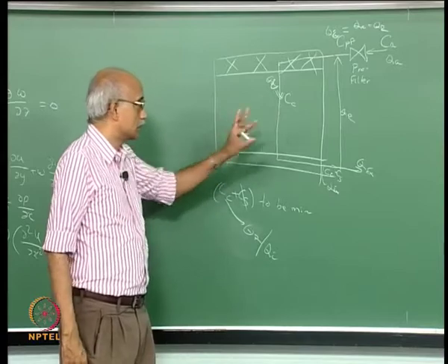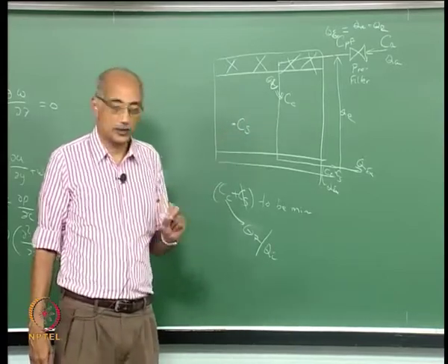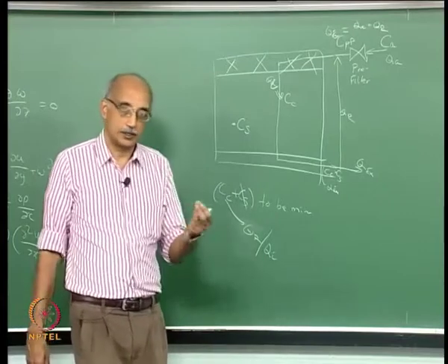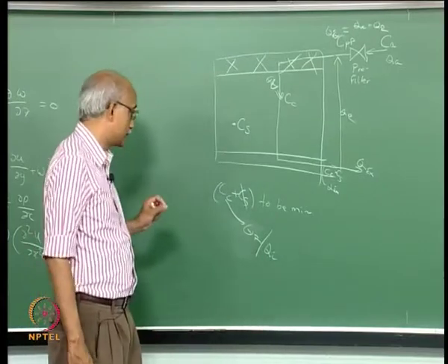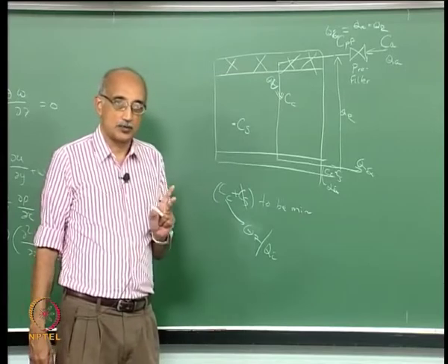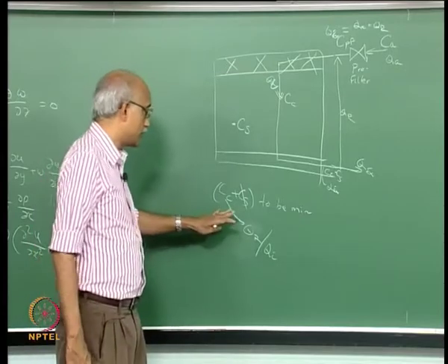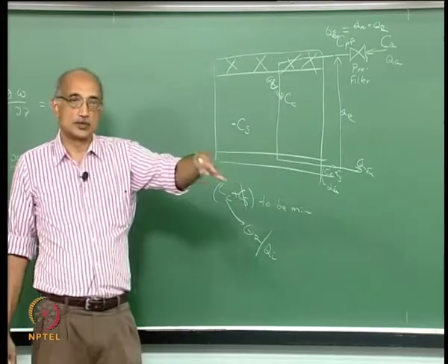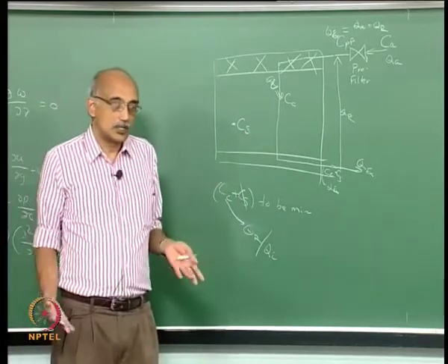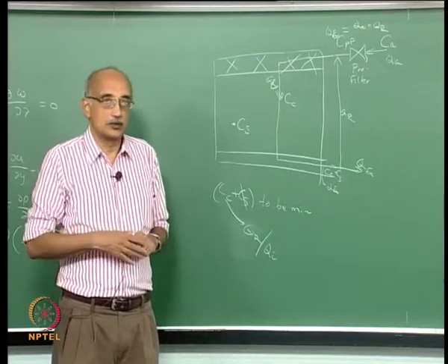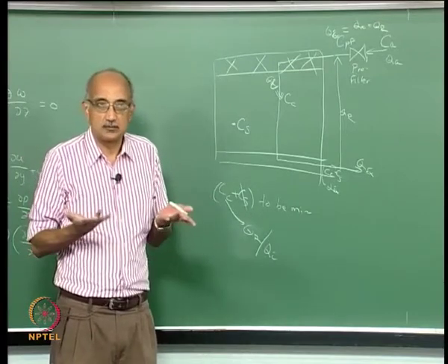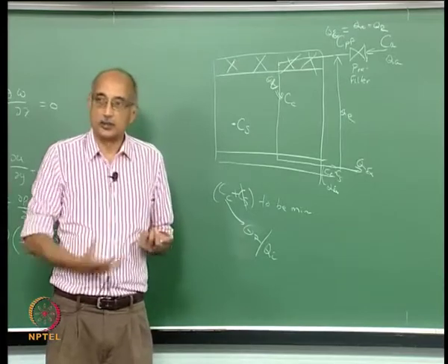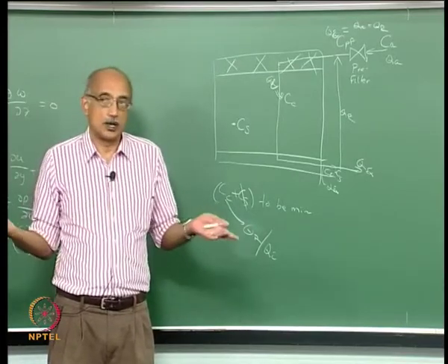For a fixed Ca value this parameter really controls the cleanliness of the clean room, but on the other hand it is a constrained minimization problem, right. You cannot say, for example, if the source inside the clean room is much greater than the source outside, logically you would say make it 98% recycle and only 2% makeup. That is not practical because you really cannot handle that volume of air with a pump and get it recycled, especially in a large clean room.